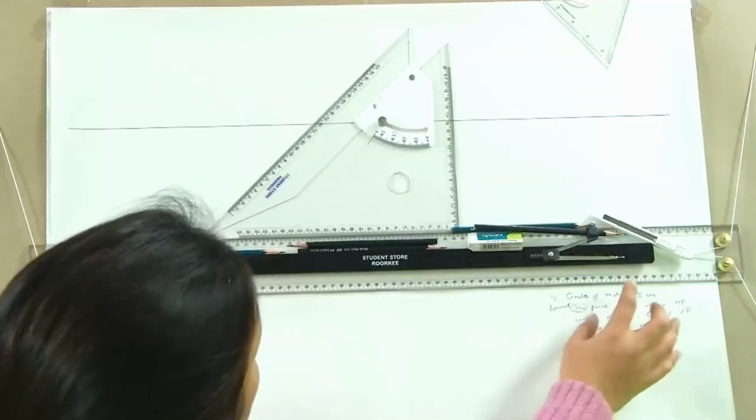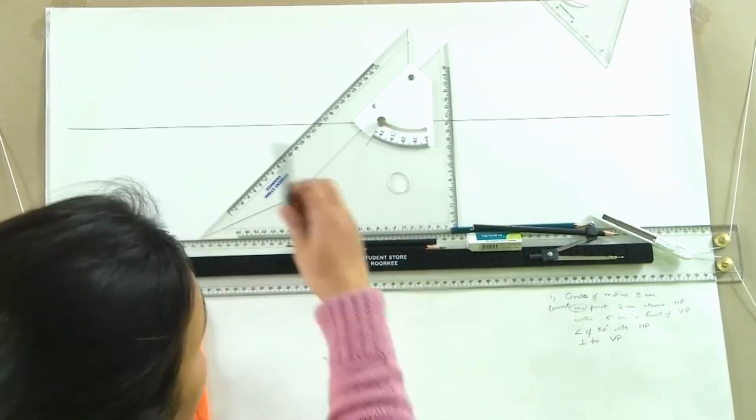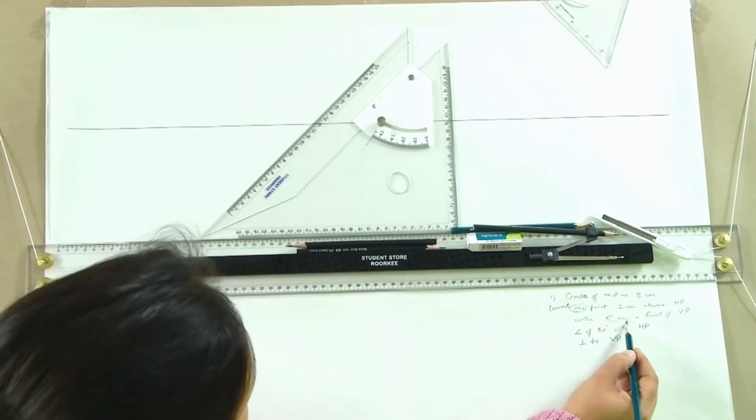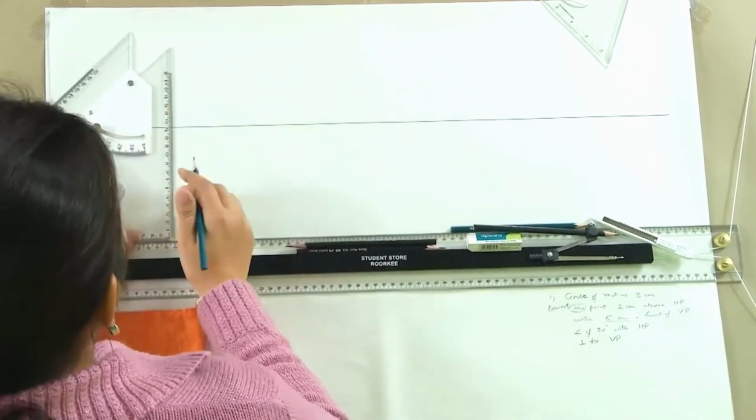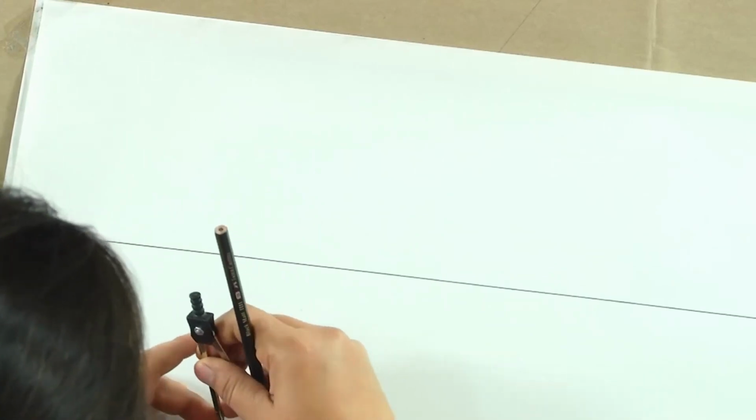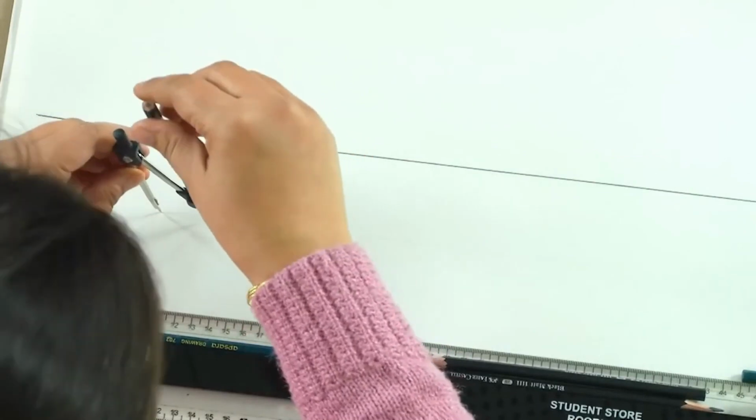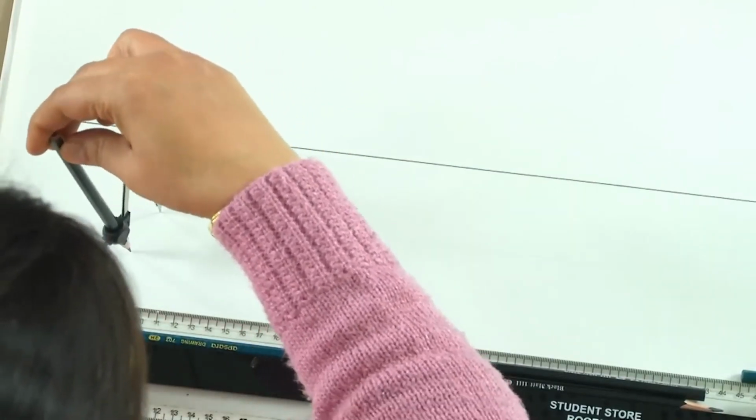Now to start with, we will have to determine where the circle is. What it says is that this circle has its center 5 centimeters in front of VP. So what do we take? We just draw a line 5 centimeters in front of VP, so it will be seen in HP. This is the line where the center of the circle is going to lie. Now this circle is of radius 3 centimeters. So we take 3 centimeters and, keeping the center of the circle on this line, we will draw